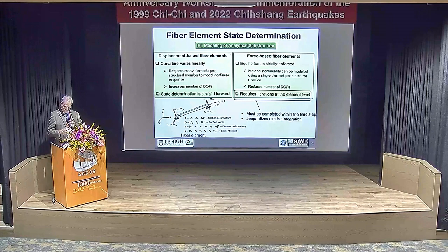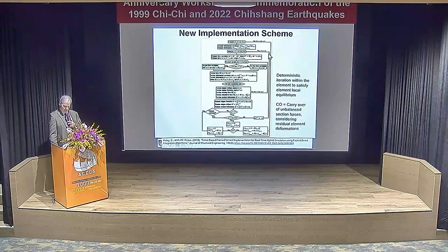If it doesn't converge, you run OpenSees, and if you don't pay attention to whether it has converged, it will just go to the next time step, and sometimes it will blow up on you. It won't work well. So this is very important.